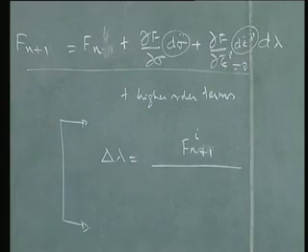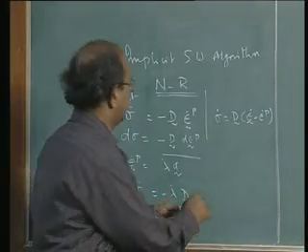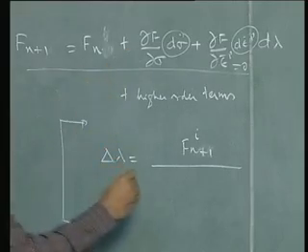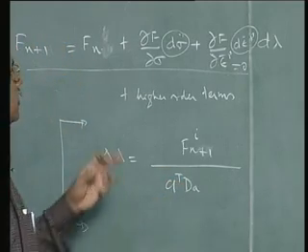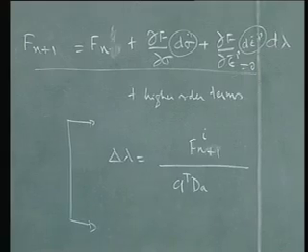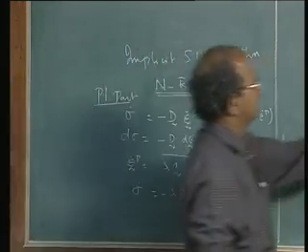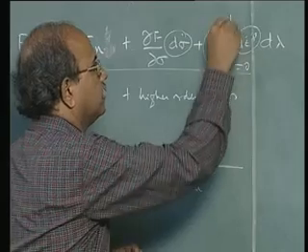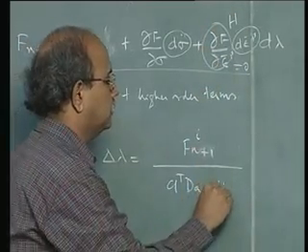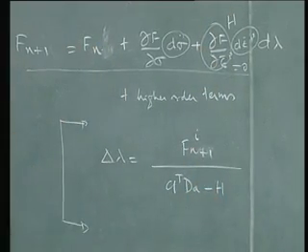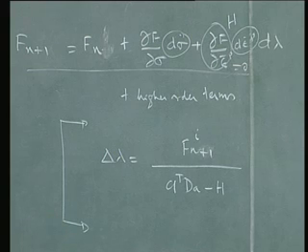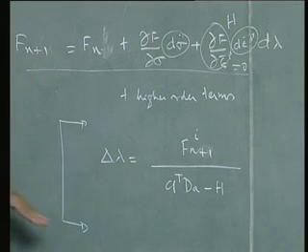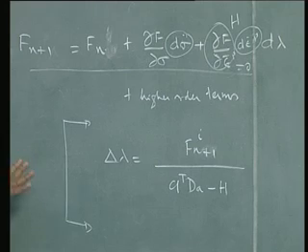So this d sigma, okay, this term there goes to this place. So you'll write that a transpose D a, okay, is what you will get here. Then for this term happens to be h, so minus h. Okay, so that's the first expression, what you have for delta lambda, and with this you can generate a Newton-Raphson loop. I'm going to leave it at this place.